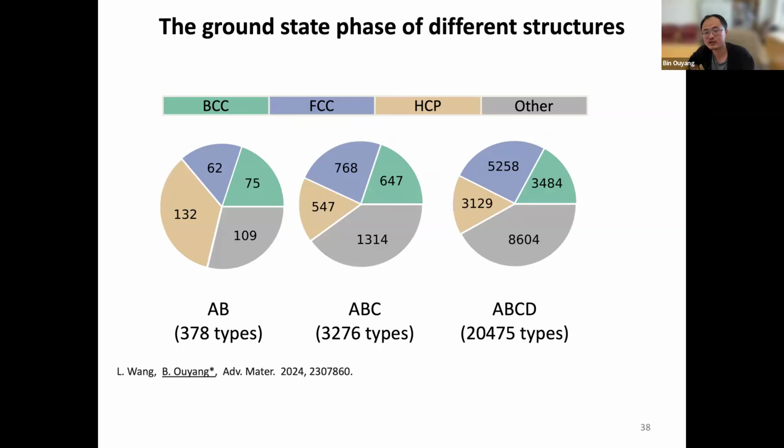If you think about mechanical properties, if you need plasticity, typically you prefer FCC rather than BCC because you just have more slip systems. Dislocations are more mobile in those systems. But when you mix random alloy elements together, you are not so sure whether you're going to form FCC or not. So as a theoretician, I'm trying to think, can we predict that, to really free synthetic people out of the combinatorial experiment?